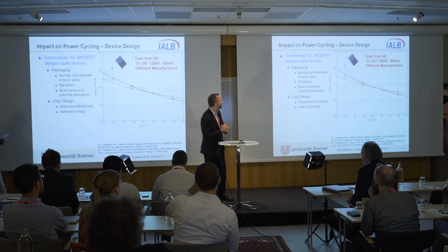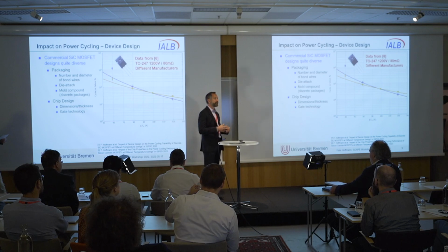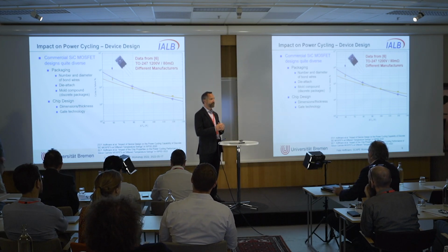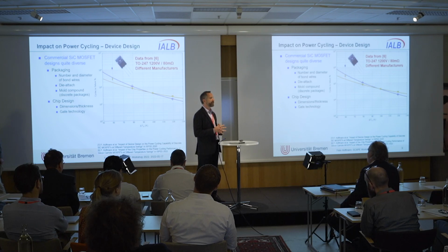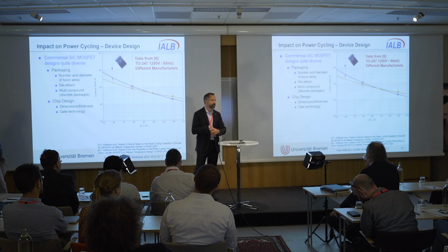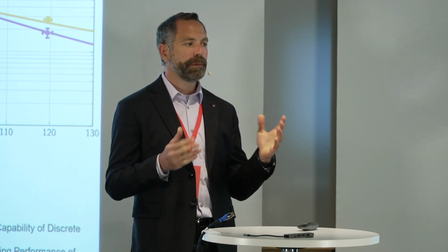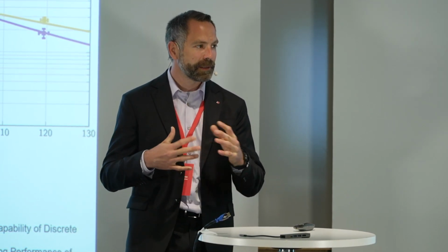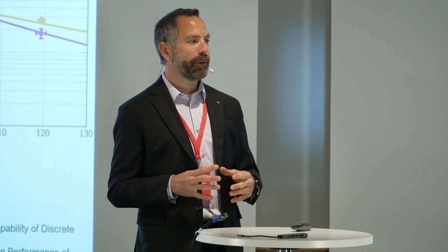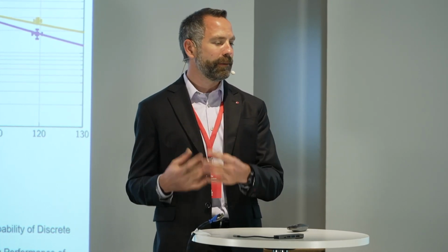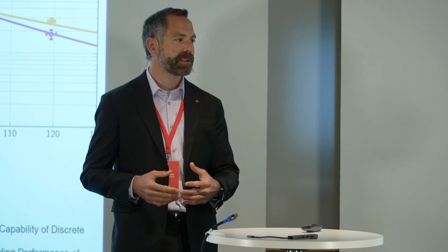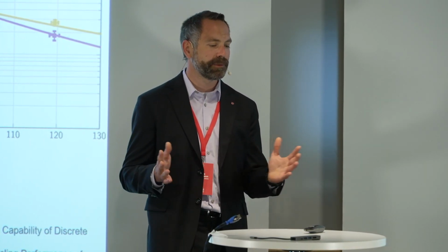Of course, we also tried to use more sophisticated models. However, they were not really improving the accuracy on those parameters. So if you want to have a rough estimation, the simplest approach is the Coffin-Manson. For all the others, you need to have a lot more tests in place and vary a lot of parameters to obtain the parameters of more sophisticated lifetime models.